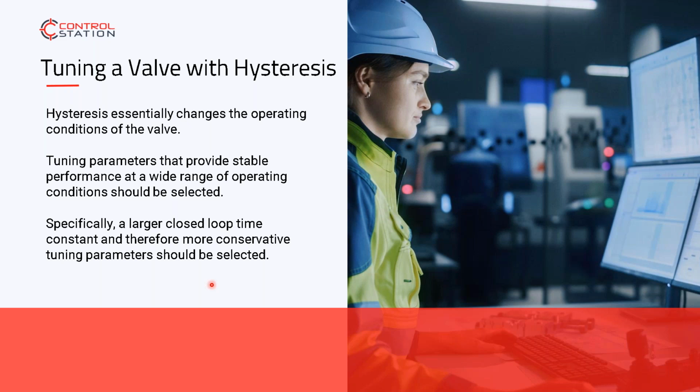Those should be the only reasons that you retune a system: because of mechanical deficiencies. And unfortunately, it happens regularly that people go, can you retune that loop? It's not performing. You're retuning for mechanical issues.